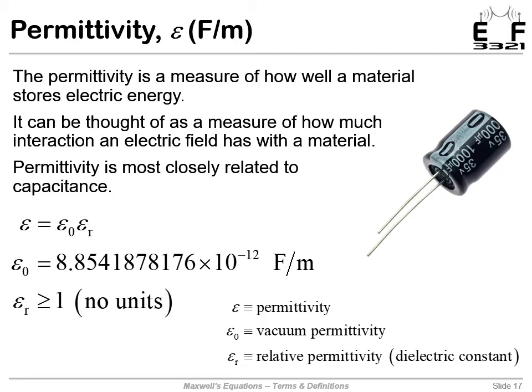Everything else has a higher relative permittivity. Plastics have a permittivity around 2.5. There's ceramics that have a relative permittivity 10 to 20. These are also much more convenient numbers to use than to express just the overall permittivity, which will always have a 10 to the minus 12 sort of factor to them. And that's just less convenient to talk about.